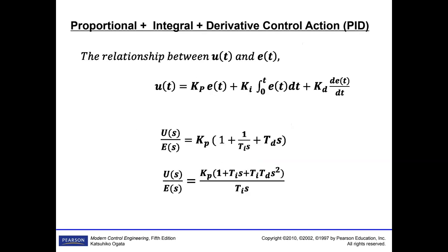the time domain equation, for example, is important. You never forget that. You are adding a KP here, KI here and KD here, but your controller transfer function is the controller output over the error; the input is error and the output is the controller output.